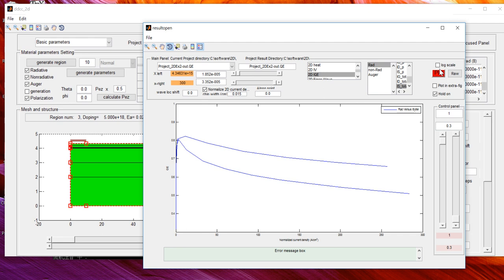For the IV, it doesn't overwrite the file. It merges the file, it doesn't overwrite. Do you know why we don't overwrite? Because usually in our real case we want to run a lot of simulations on different nodes.